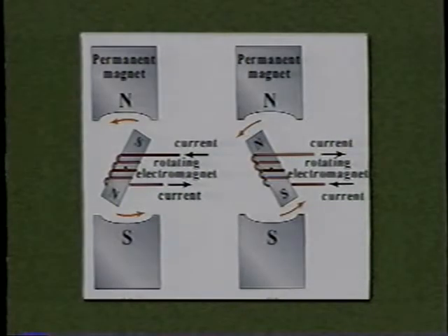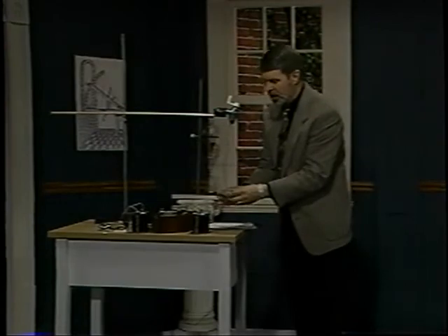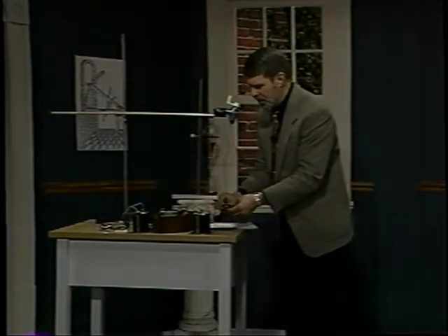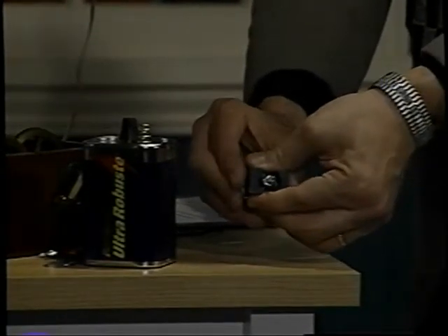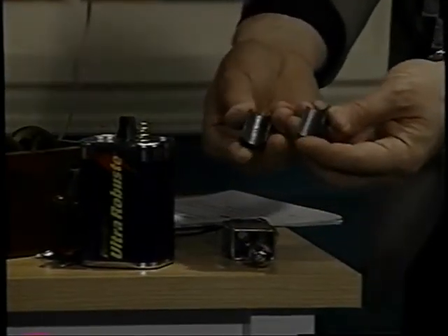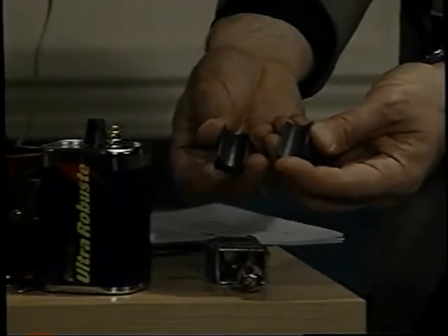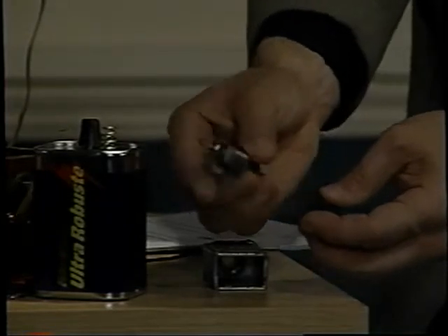And then we come to electric motors. Electric motors are a pervasive use of electromagnets in our society, an incredibly profound ability to convert electrical energy through magnetic energy into kinetic energy. Let me show you how a motor works. You simply have a push-pull effect of one set of magnets against another. In many simple electric motors, for example, the kind you'll find in most electric razors, you'll find permanent magnets which are fixed into the casing of the motor, and then you'll have a rotor which has little coils of wire which form electromagnets.